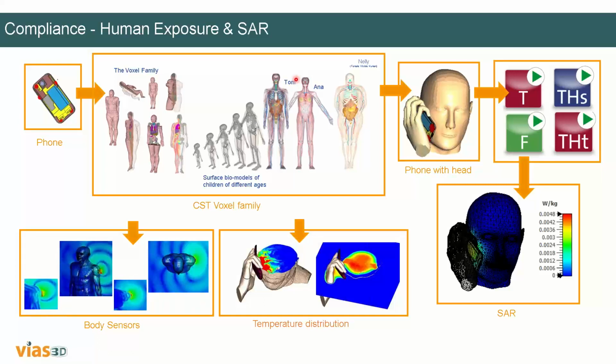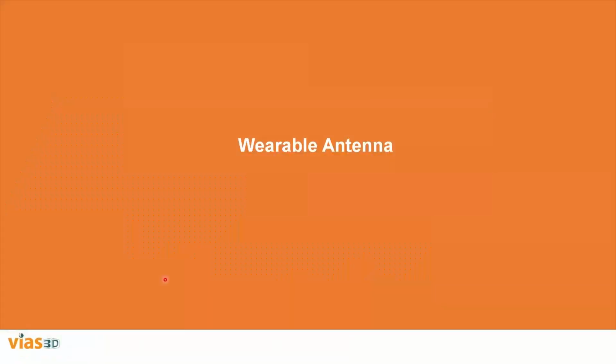So you get one result at 2 gigahertz and another at 5 gigahertz. It is always better to tune it for the intended frequency, and that capability is already built into the model. You can place your antenna or mobile phone along with the antenna, and see the SAR analysis as per the FCC standards. You can even understand the temperature distribution caused by the antenna placed near the phantom. These are some of the most important studies conducted by every mobile manufacturer and any handheld manufacturer.